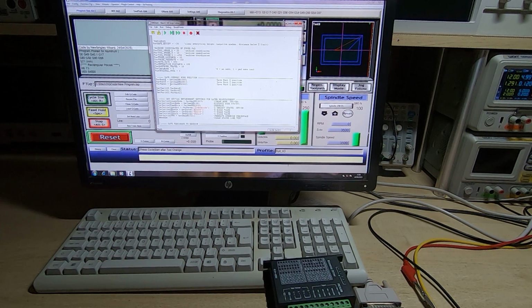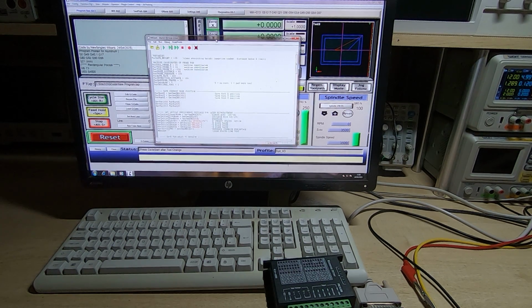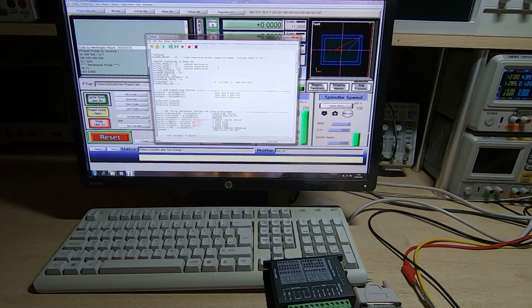We then get some values that we want to retain. Bear in mind this is normally coming up during a milling operation, so we're part way through a G-code file when we normally run this. The first thing we do is save the current X, Y and Z locations, and that's the G54 locations.